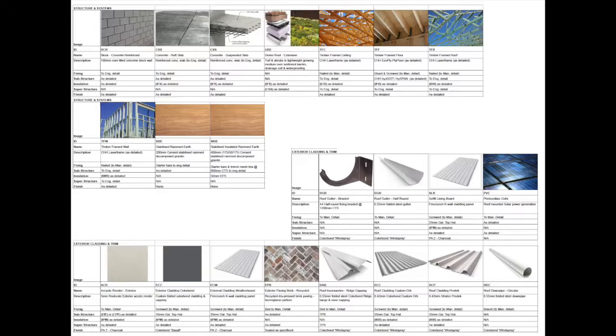And then finally, we're going to need to show external finishes. I typically will call that a material schedule. Council is very interested in the exterior finishes or materials that we're proposing in the project. The exterior materials may be the wall finishes, the roof finishes, maybe external floor finishes. Now, this could go further and show internal finishes as well, but it's technically not necessary as part of the DA process. In addition to the plans, we will also have a variety of reports that are necessary.